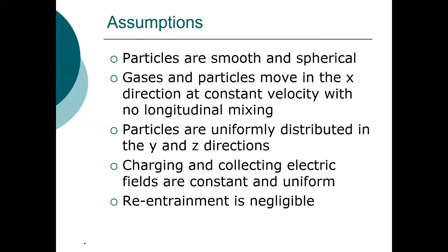The development of this equation assumes that the particles are smooth and spherical. It also assumes that gases and particles move in the x direction at constant velocity with no longitudinal mixing, and the particles are uniformly distributed in the x and y directions.